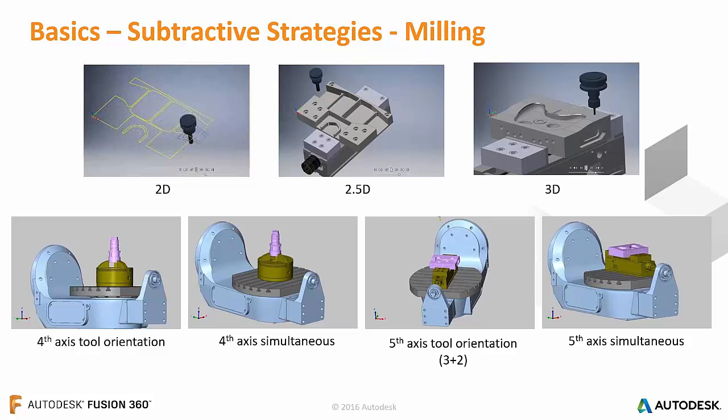You can see also that we have the 2.5D capabilities. So again, we're taking the 2D functionality and extending it to 2.5D, which allows us to work in the Z direction. In 2D we're working in the XY, in 2.5D we're working in both XY and Z. On the 3D environment though, that's where it really comes into play. In this case we're following a 3D profile, following X, Y, and also the Z direction.